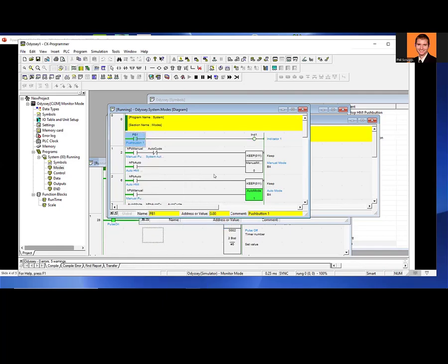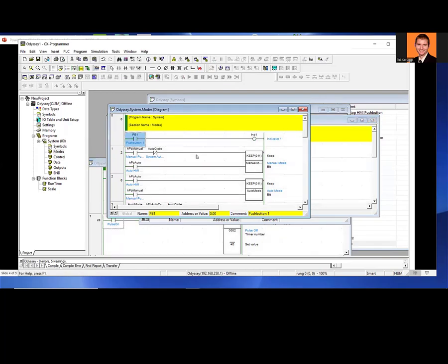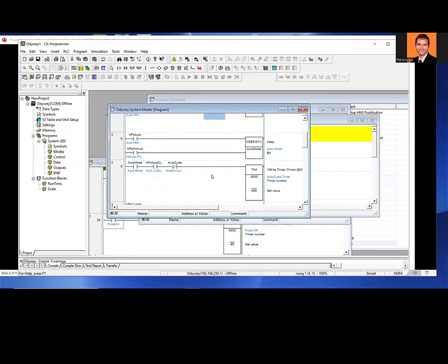I'm going to set this off. And this little icon right up here says Work Online Simulator. This is a really cool thing that Omron has, that you can simply be typing your code in and simulate it at any time. This is much like the Siemens Step 7 simulator. There's just a little cloud. You open it up and it brings up a little fake PLC, and you are downloading to the fake PLC. So whenever you put new code in, it automatically downloads to it and runs right in the background.